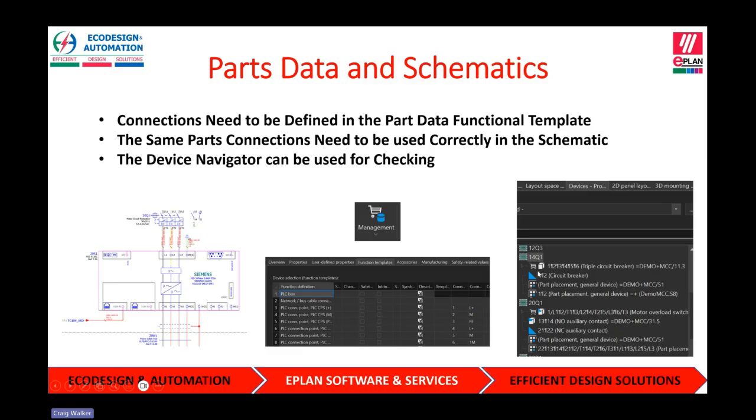This won't route. It won't understand this because it can't see that they're actually linked. If we look at this 20Q1 down here, we can see that it is actually linked. What we've got is this blue triangle sitting on top of the white square. This is under your device inspector, remember? So here it's saying that the white square is, we've placed it correctly on the schematic, and the blue triangle says it's correctly defined in the functional templates. And because they're over the top of each other, it's saying ePlan can fully understand that they are linked. There is a connection between them.